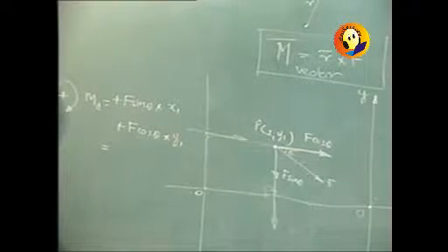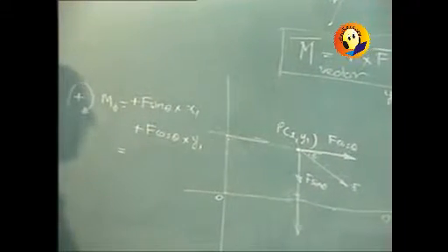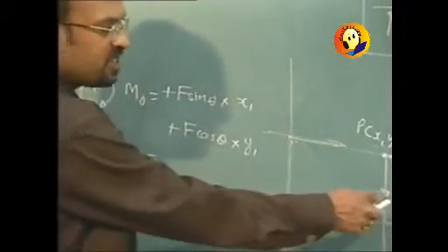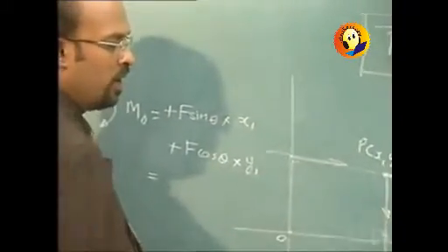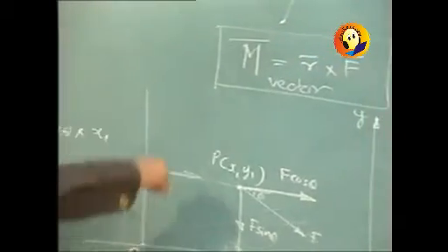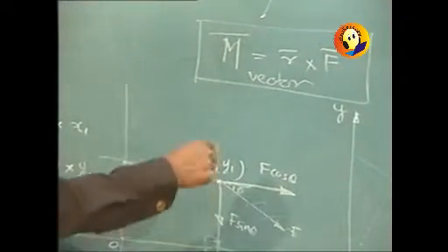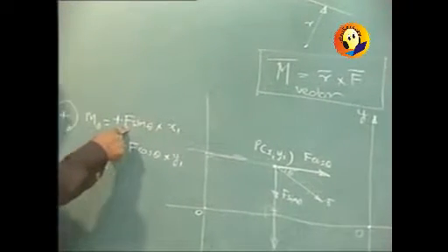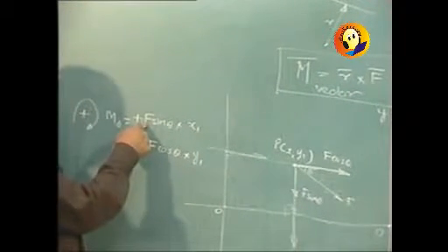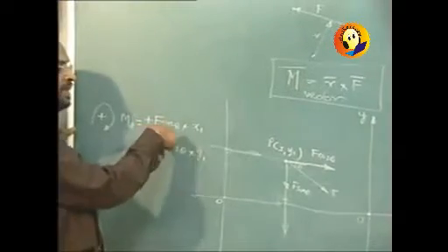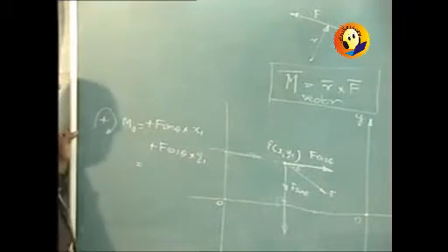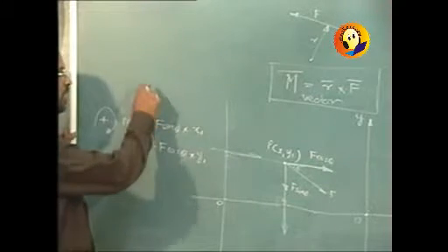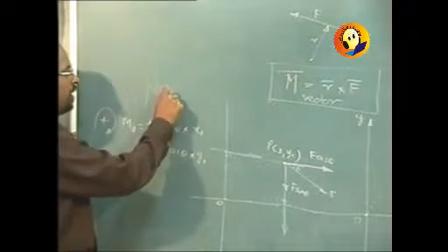Now, one of the common mistakes that anybody will commit over here, let me point out that mistake, because the F sin theta component over here comes out to be negative. It is in the downward direction, and if you carry this particular negative sign, then you are likely to make the mistake, because then that moment will come out to be a negative moment, which should not happen. And so when you are going to use these components over here, use their numerical values,